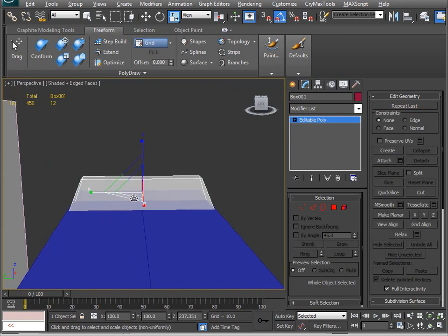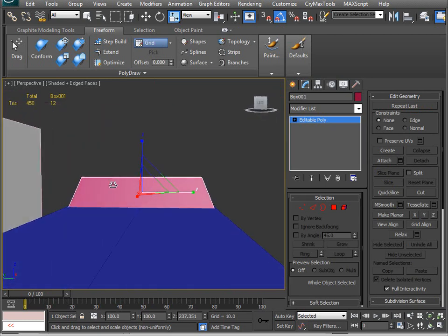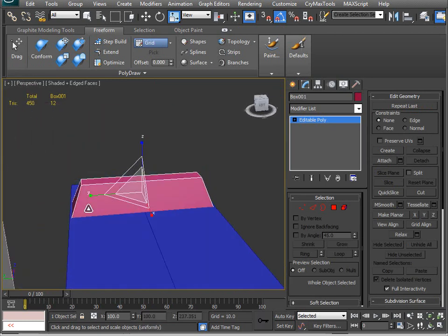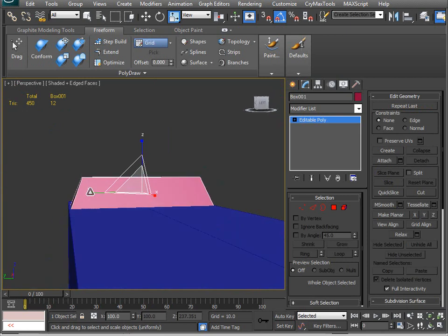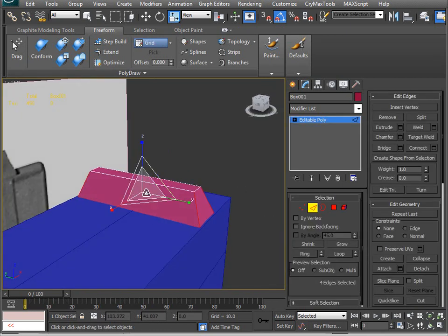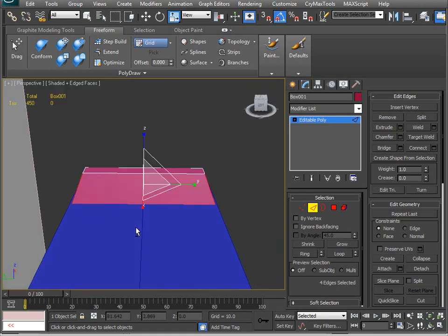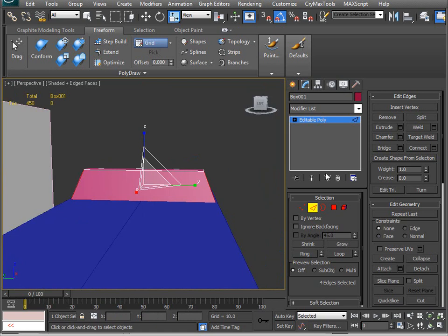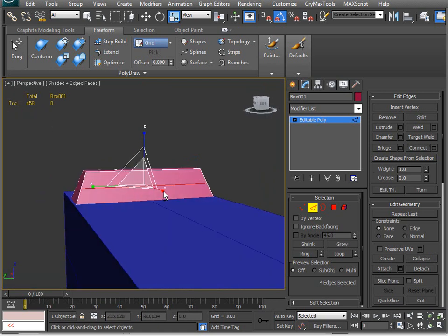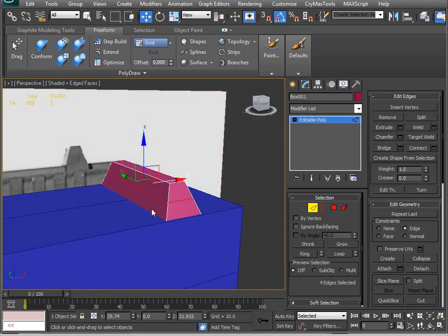Okay, now this also has a space cut out for it. Let me hit J real quick, get rid of that box. Hit Alt X. So what I want to do is cut a box out of this. And this is another simple way of doing this. Could obviously boolean a box out of it, but then I'd have to align a box and all that stuff, which wouldn't be a big deal, but there's multiple ways to do everything. So I'm just going to connect there. I'm going to go ahead and constrain by edge.